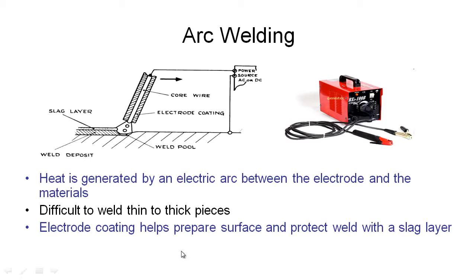Once the weld has fully cooled, if we want to expose this weld and perhaps do another pass of weld, then we actually have to chip off this slag layer once it solidifies with a hammer and make sure we've removed all of that before we do the next pass on our weld